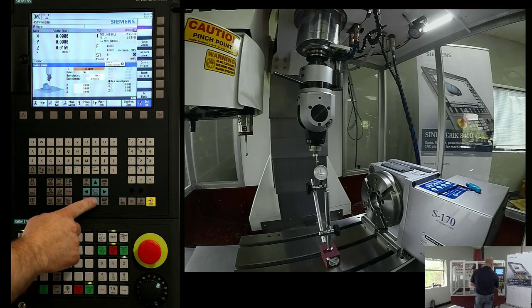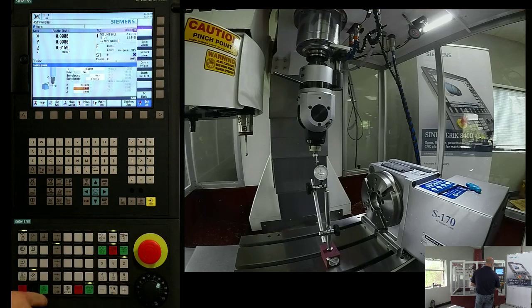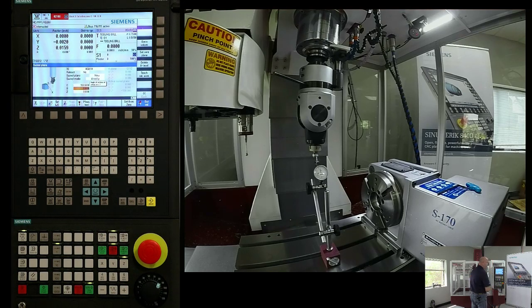Now if you notice the numbers, as I swing my rotary around, the system is going to offset the physical axes. So if I then command the machine, remember this is static because I have a basic manual axis, but if I command the machine now to move to 0, it will compensate for that runout.